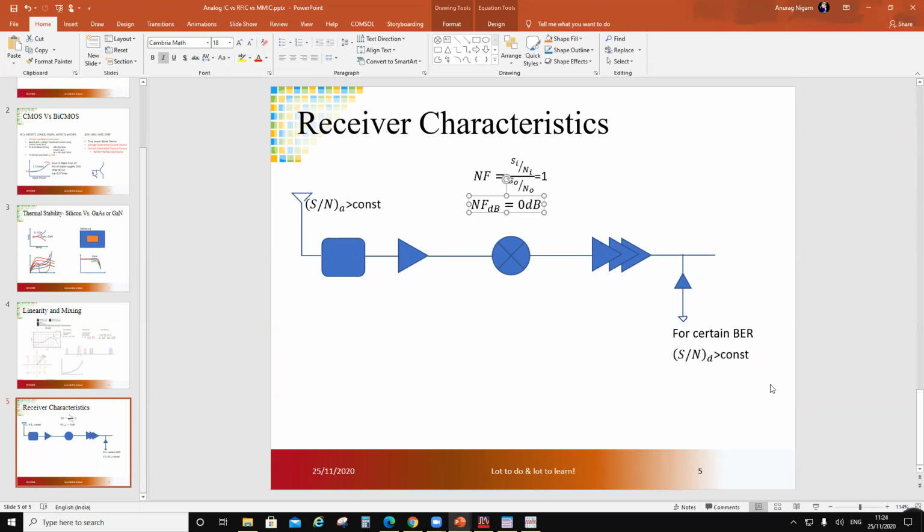So the overall noise figure, or noise factor, for this receiver is going to be signal to noise ratio at the input, which is this, divided by signal to noise ratio over here, right? So basically then this number NF would be signal to noise ratio at the antenna. So this will be that. And let's remove the ideal case. And then this guy.